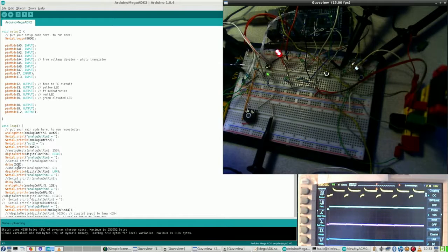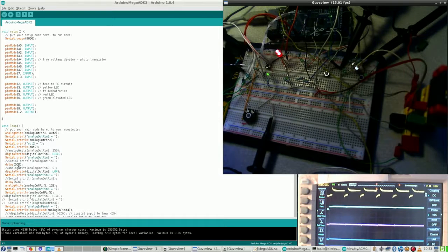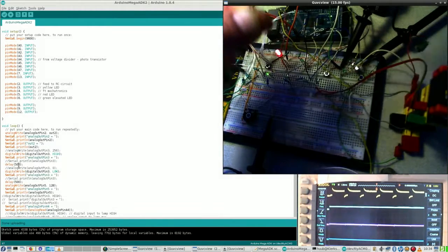And normally LEDs have a flat side, and if they don't, you can see it inside by the way it is constructed, and in this case I can't properly see it. And I think with this LED, this is the way of plus and minus.